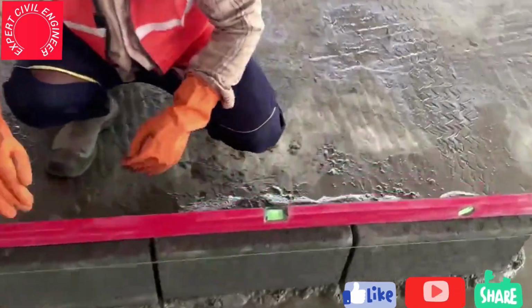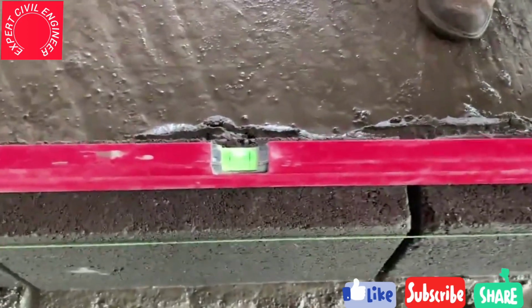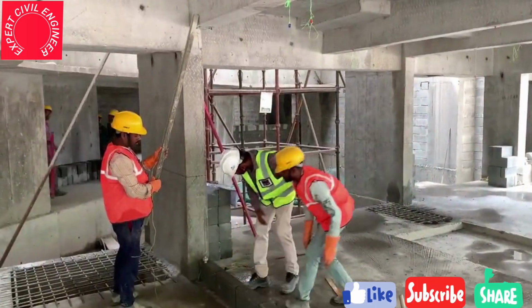Additionally, the top level should be ensured using a spirit level before commencing with further blockwork. The plumb checking process should be carried out in reference to the existing beam located just above the blockwork.